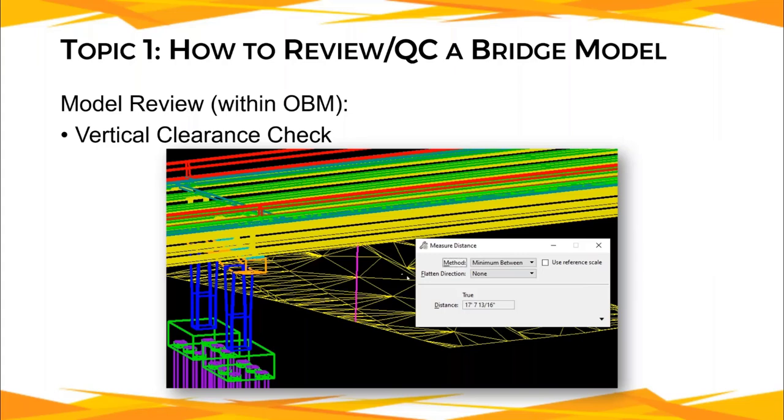After that, you'll likely have some 2D line work in the survey file that will represent gutter lines. So you can use those gutter lines and clip out everything outside of those limits. And then within the Civil tab, there's a model terrain group. We'll basically go through and clip that terrain based on a 2D element that we've selected.